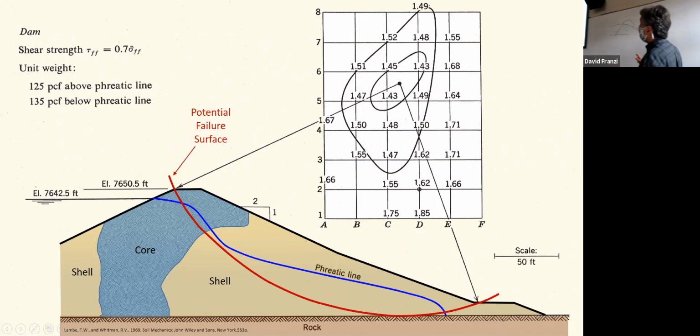All right, but all of that goes into all of these things. So if you design, let's say you have a highway embankment, and you want to make sure that it's going to be really safe, you can practice with some different designs, right? You can say, well, what if I made this a 2-to-1 slope or 3-to-1 slope? Wouldn't that save you some money? Well, you do that, you find out your factor of safety is poor, then you can lower it. So you get into that range of safety factors that you want. All right, so these slopes are then sort of engineered.